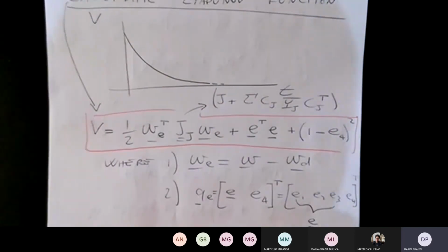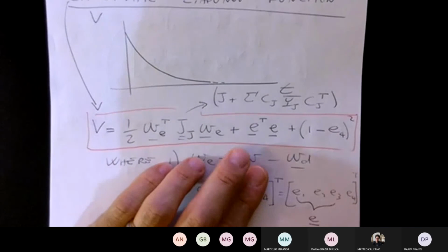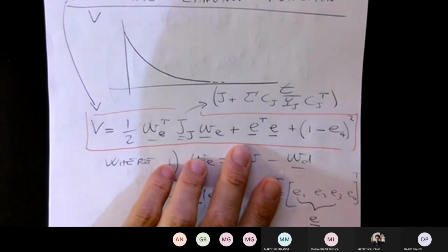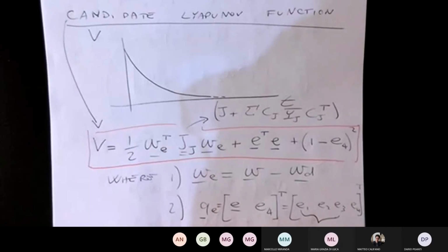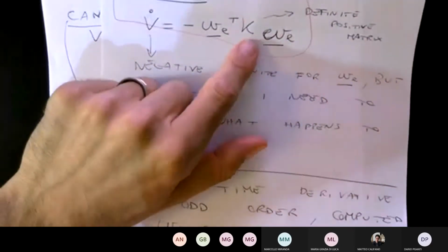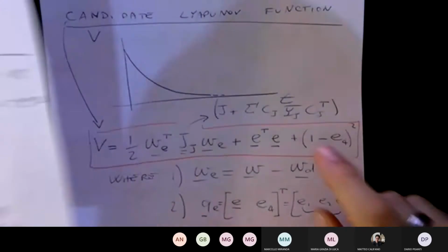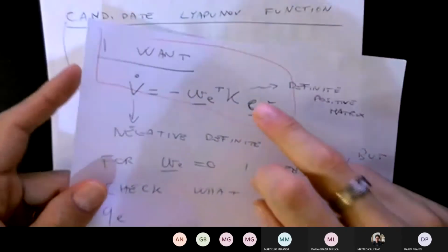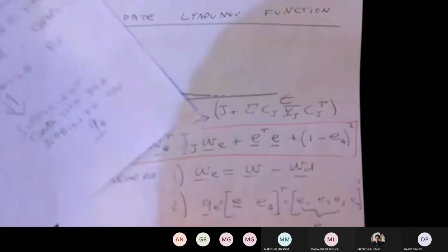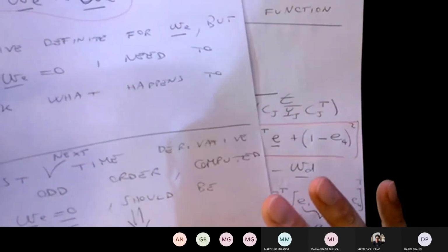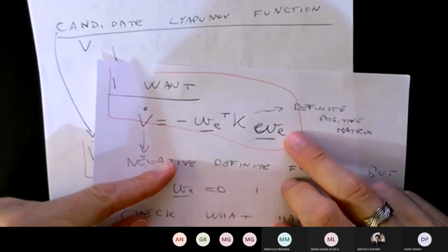Yes. We haven't derived any controller, but I am suggesting that my function of reference is this one, and then I want its time derivative to behave like this. By imposing this Lyapunov function and this behavior for its first time derivative, I've shown with all this math that this is okay also for the error quaternion when omega E goes to 0.